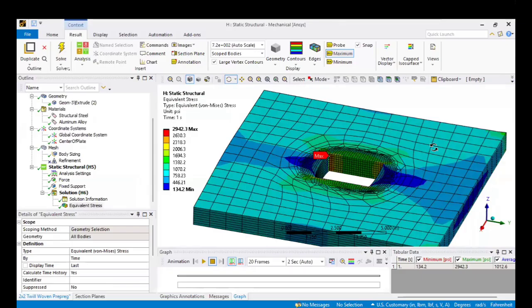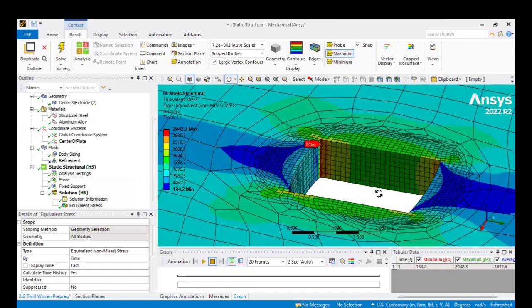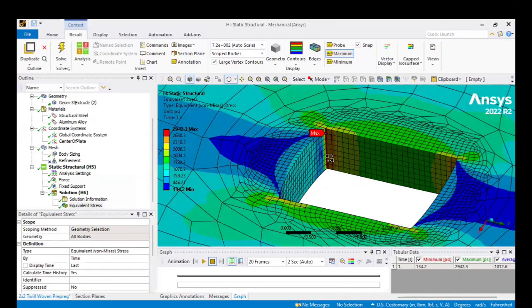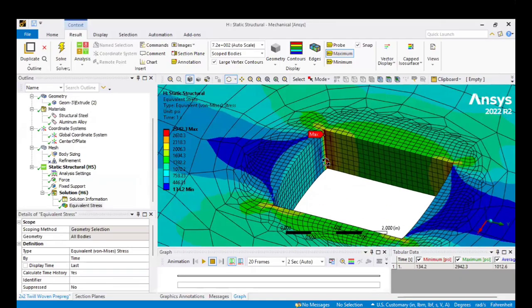I know we're just doing plate stuff right now, but I think it's important to cover the basics, like singularities. I was doing ANSYS for 6-7 months, and I still was like, singularity, I'm just going to ignore it. But I didn't really physically understand why I'm ignoring the singularity. And so, like the Professor was saying, you can run in ANSYS a feature called non-linear modeling. And what non-linear is, if you have your stress-strain curve, you're in your plastic region, right? You're permanently deforming the part. But what parts do when they plastically deform is they redistribute the stress, usually in a way that's more favorable for the part. And so that's why your stress may actually go down, but permanent deformation goes up.